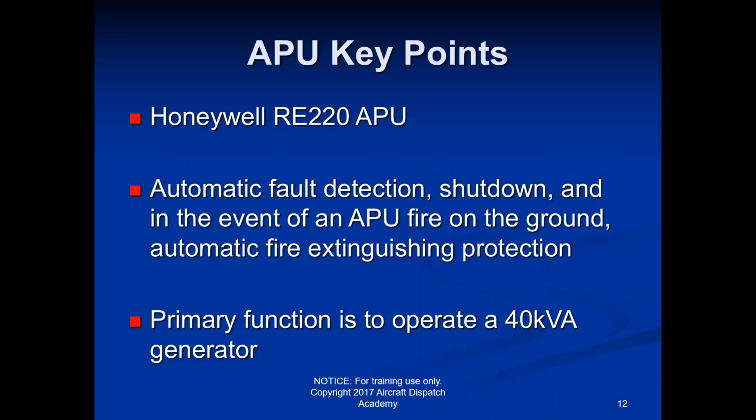The other one obviously is that the APU is used to start the engines as well. So if you don't have an APU working, then you have to get a huffer cart or an air start bottle to provide air to the engines in order to start them without the APU.